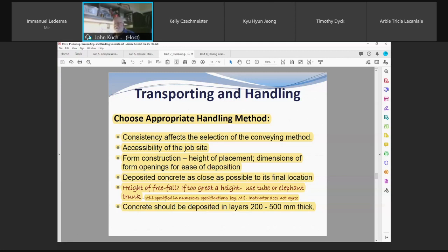When I was at Centerport, and then I left Centerport to come to the college, but I kept in touch. MI forced Subterranean to pour the concrete for those big lamp standards that you see as you're going up on the overpass, the lighting standards and the sign standards for your directions. They were only maybe 8 meters deep, caissons, because bedrock was close. They had to pump every one from the bottom up. MI would not allow them to drop that concrete more than 5 feet.